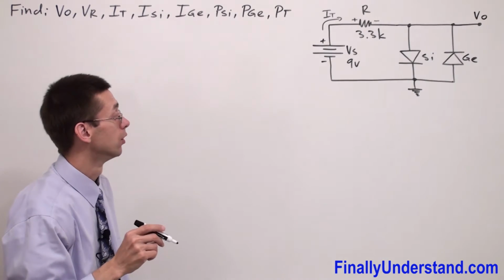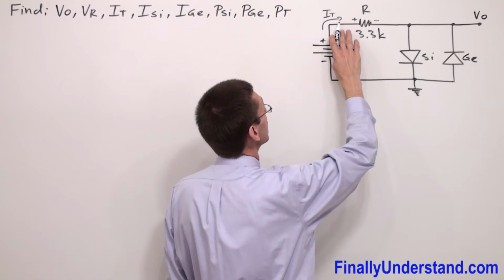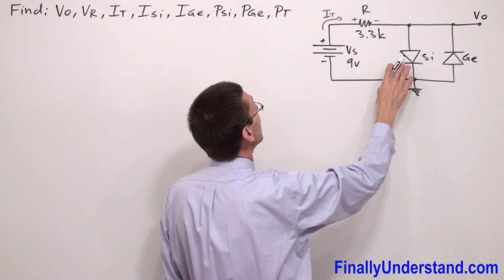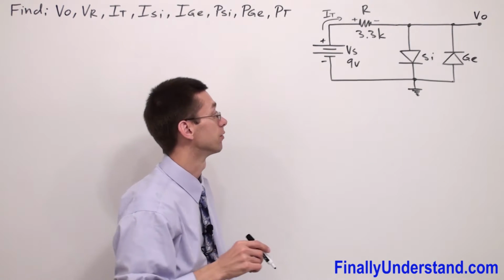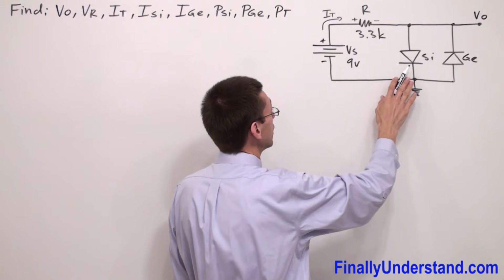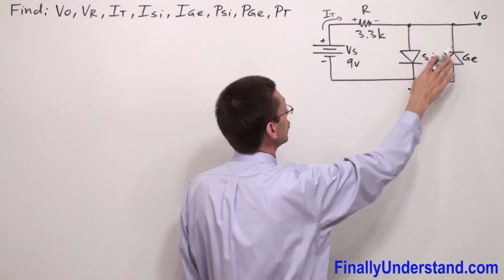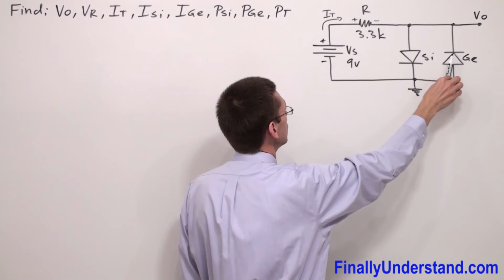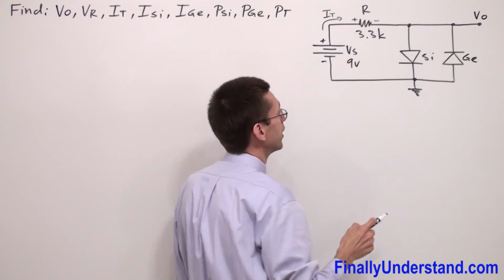It's going to be forward biased, okay? Why? Because this direction is matching the direction of my arrowhead, and this voltage is much greater than 0.7 volts. So this diode is going to work. If you look at this one, the current will want to go through this diode, but this diode is opposing the direction of the arrowhead, right? It is opposing the direction of my current.